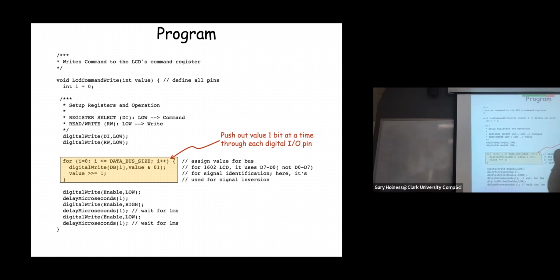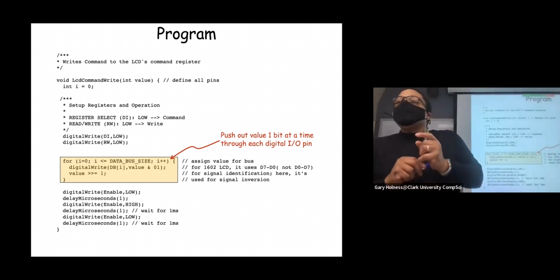So when I want to send that value, 00001010, to the data bus for the device, I'm doing it one bit at a time. I first send the 0, then the 1, then the 0, then the 1. I'm doing that on different I/O port pins on the Arduino, which are connected physically to different data bus lines on the device. Does that help clarify?